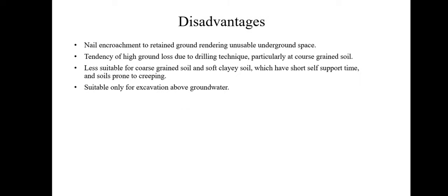So next are some disadvantages of soil nailing. High ground loss may occur due to drilling from time to time, particularly in coarse grained soil. It is only suitable for excavation above groundwater, and less suitable for coarse grained soil and soft clayey soil, which have short self support time, and soils prone to creeping.